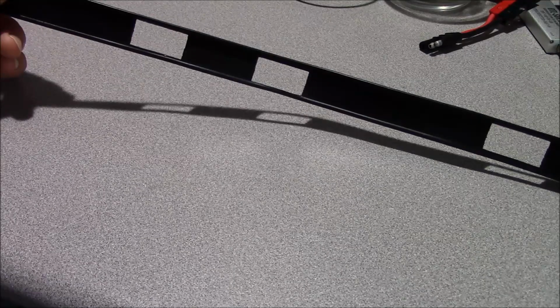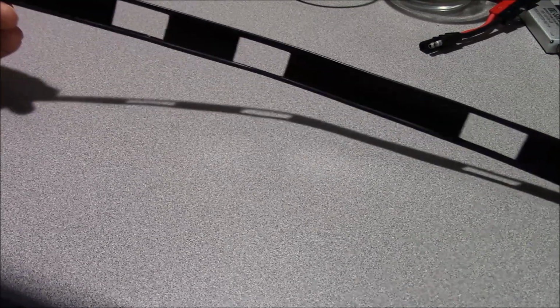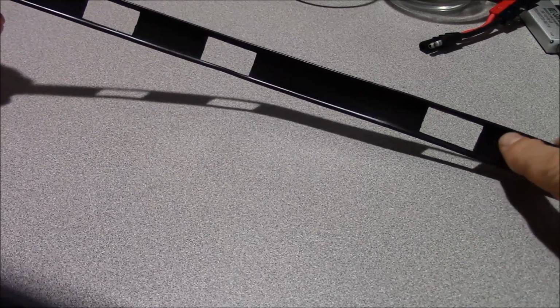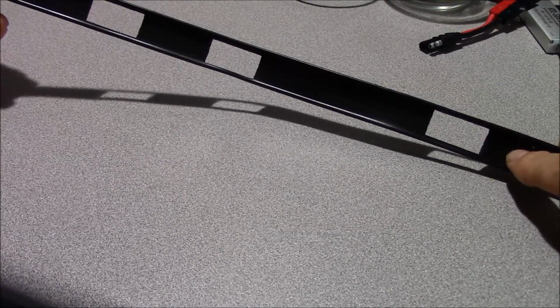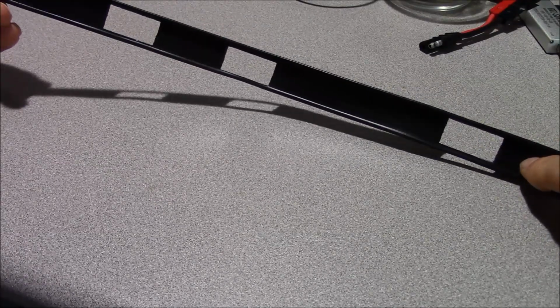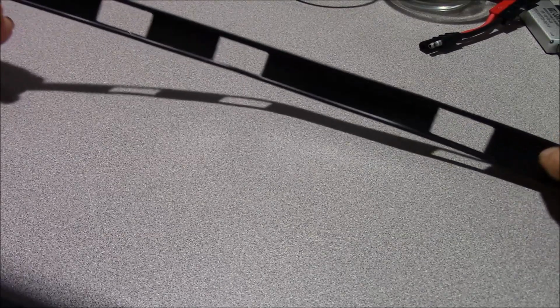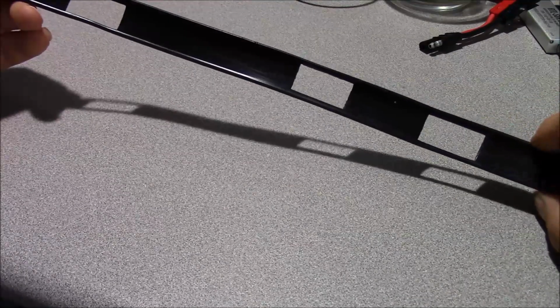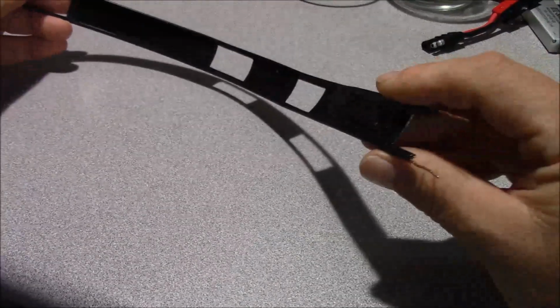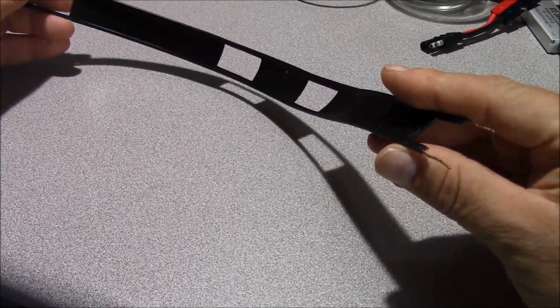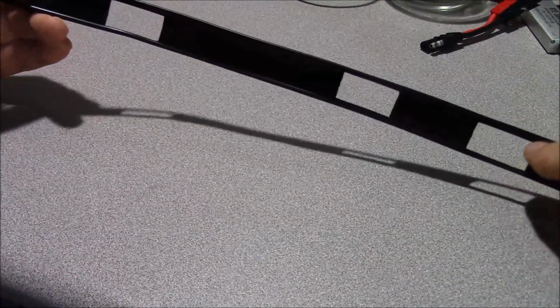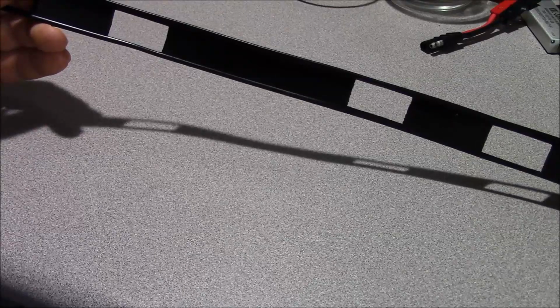So when selecting material to build our balanced feeder, we need to look for consistency. We need to have consistency in spacing. Now, it doesn't necessarily have to be as widely spaced as we see here with this 450 ohm window line, but it needs to be consistent throughout the entire length of the feed line. The conductor size should be consistent with one another, and the insulation quality should be consistent as well.